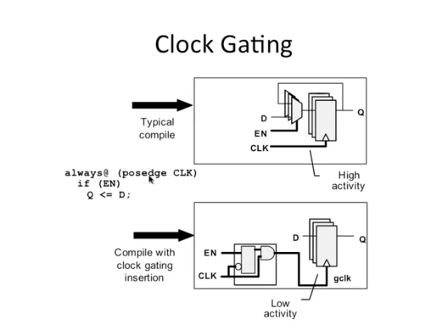And how do you write that in Verilog code? You have always at posedge clock, if enable, assign D to Q. That can be implemented like this, where you have a bunch of flops. D is a bus, and then you have muxes in front of it. If enable is low, you recirculate the old value.